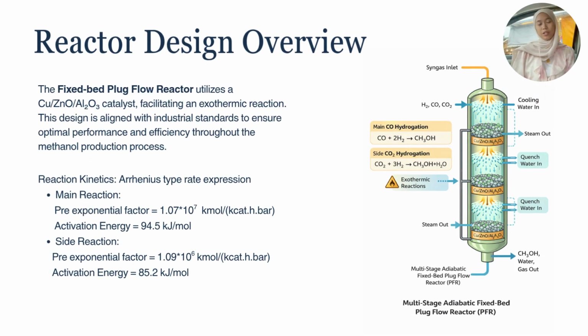My name is Aisha. I'm going to explain about the reaction engineering part. This setup is widely used in industry because it provides high efficiency and supports the exothermic reactions involved in methanol synthesis. The reactor is designed as a multi-stage adiabatic system, meaning the reaction occurs in stages with cooling in between. This helps control the temperature rise due to the exothermic nature of the reaction and prevents catalyst deactivation.